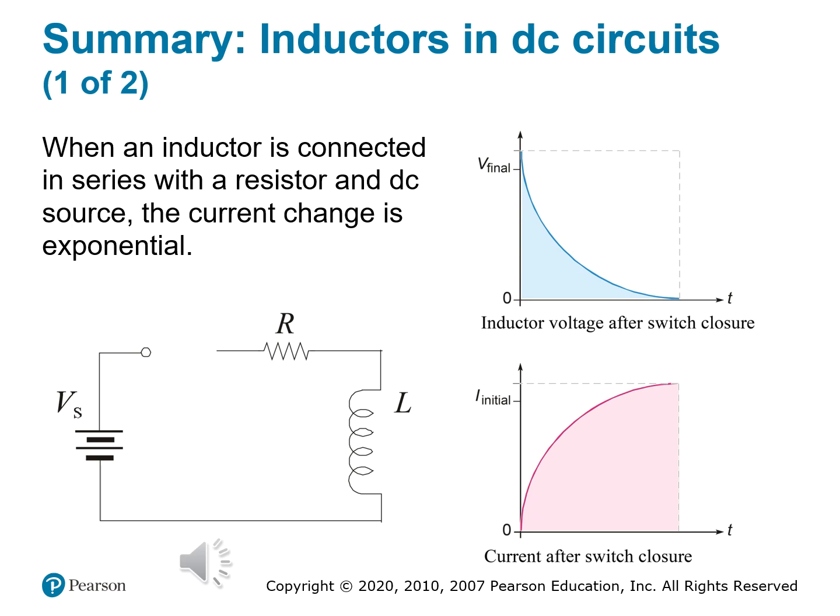You have a DC source, V sub S here, that's connected in series with a resistor, let's say R1, and an inductor L. And at the moment that switch is closed, you might expect the current to instantly jump up to V sub S over R. But inductors don't play that way, at least not in classical physics or in our universe, unless we're discussing maybe quantum inductors or something that doesn't exist, where two things can actually exist in the same point, in different points in the same time, right? So that's why we don't have instantaneous anything here in the real world. But because inductors resist change in current, the current rises exponentially, not instantly.